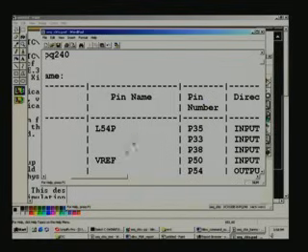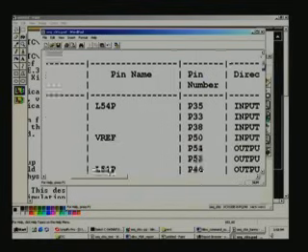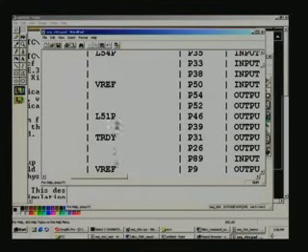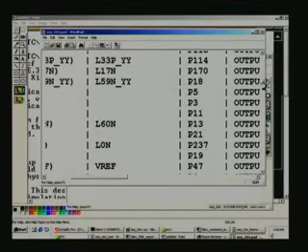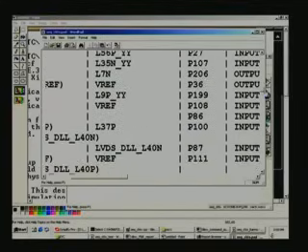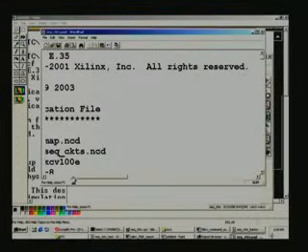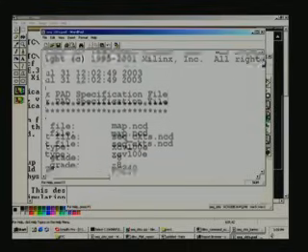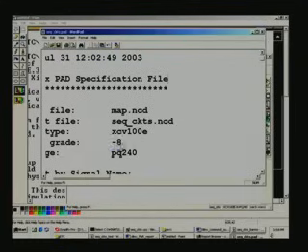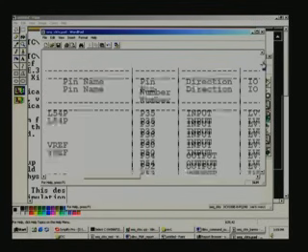Pin number is here, pin name is also given here, and in this you may have so many other pins relevant to the particular FPGA, and for programming some reference and some ready and so on. There are so many pins there, even VCC, ground, all that will be there, because it is a full listing of all the pins pertaining to that particular package that we have used earlier. This is a device you remember was 100, speed 8 and PQ 240 package. So these are all the pins that you have already seen here.